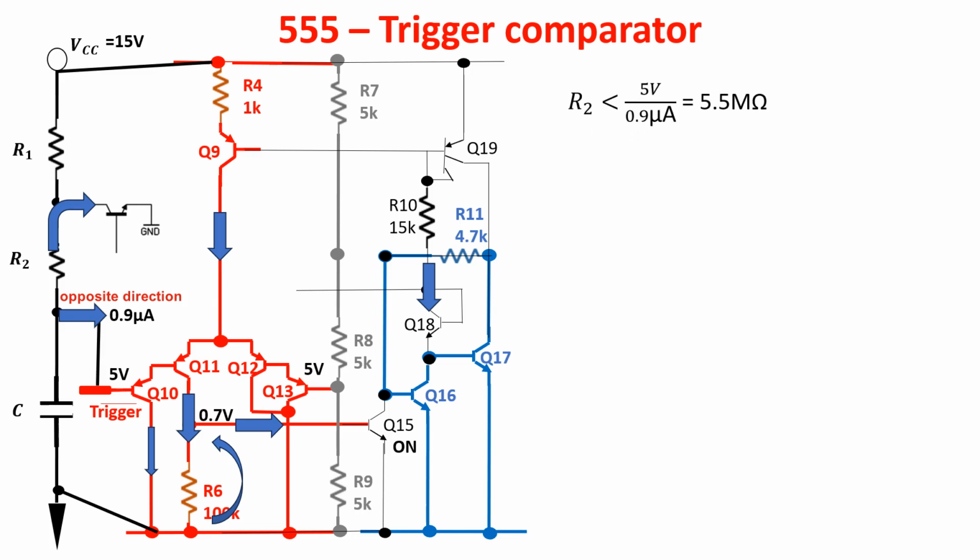Being the tail current around 80 microamps, the beta is between 90 and 160, which looks quite low to me, even considering that it is a PNP Darlington and one of the two transistors is a lateral PNP with a low beta. Write to me in the comment what you think about it.